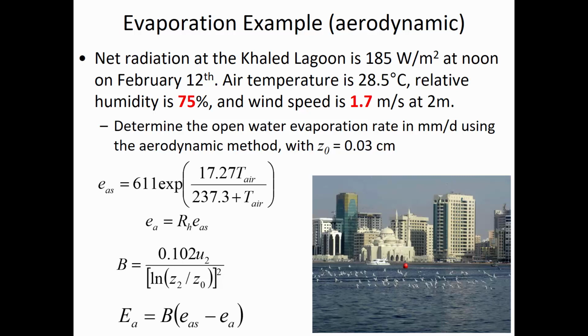So the E sub A is the actual vapor pressure, and so it is the E sub AS times the relative humidity. Okay, so we know that maximally there could be 3893 pascals, and the relative humidity is 55%, so we multiply that by 0.55, so it's 2141 pascals.